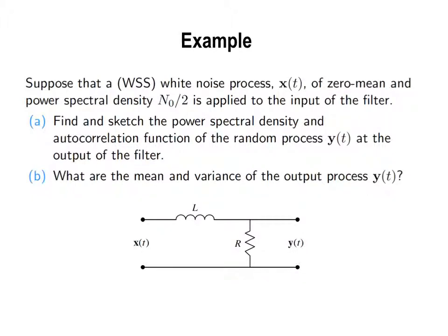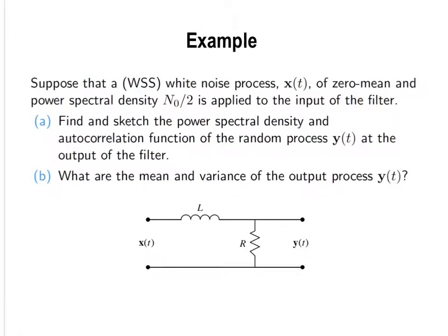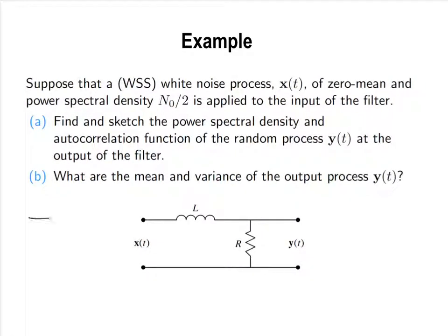Last time we have been discussing how you look at noise as a random process, and then how you can get its power spectral density, right? So at time domain, you have the autocorrelation for noise, which ideally would look like this, something like a delta function. Approximately a delta function, and we assume it is a delta function. And this peak, of course, happens at tau equals 0. So at time domain, it's a delta of tau multiplied by some value, and that value we call N naught over 2, okay?